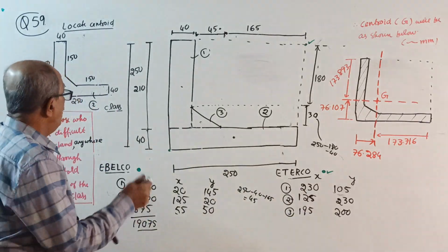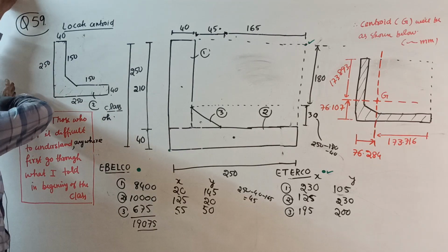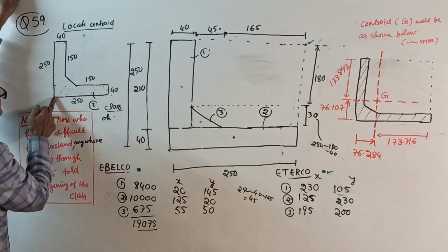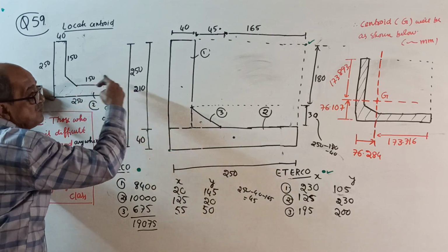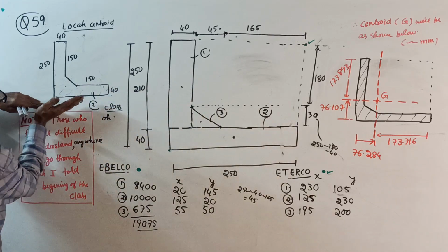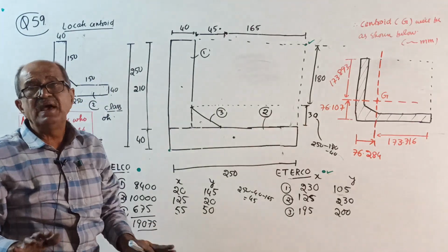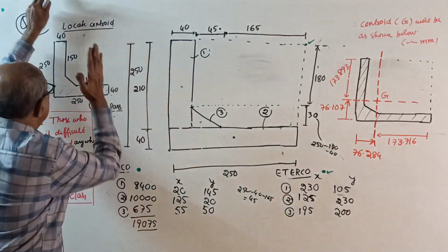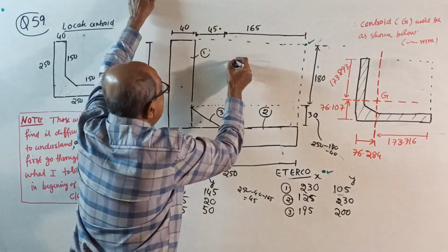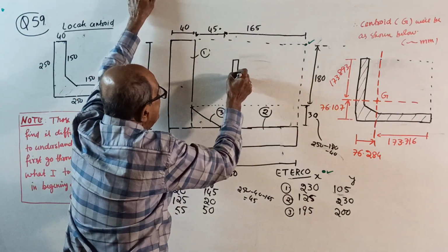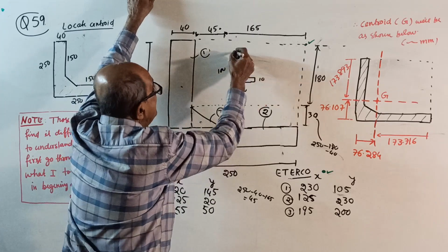Class. Oh, right here. How is the arrangement to right side from left side? See, 250, then thickness, some triangle, offset 150. Same is the arrangement from bottom to top. Oh, therefore, XX, YY are not symmetrical. Remember, symmetry, this way XX, YY symmetry is not there, but like equal angle, see, right, equal angle. This I told you earlier. Equal angle, 100, 100. Then thickness is 10 and 10.